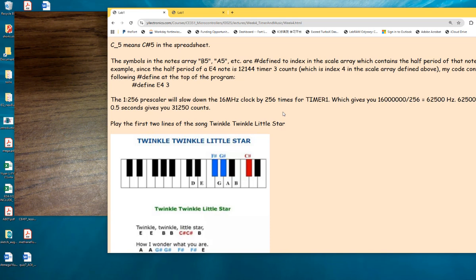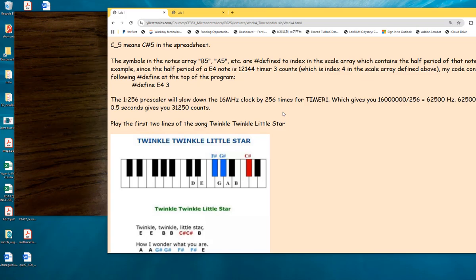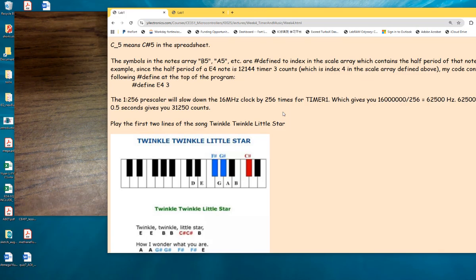So you need a timer for the duration first, and during that duration, before you stop it and play the next note, there's a break in the middle, because it's twinkle, right? So that break has to be handled as well. During that duration, you are playing that note. It's a certain frequency, so you need another timer to do the oscillation. So you need two timers, and the break can be a simple microsecond delay. We don't want to involve three timers. So it will be a nested timer controller. Two timers, one controls the duration.